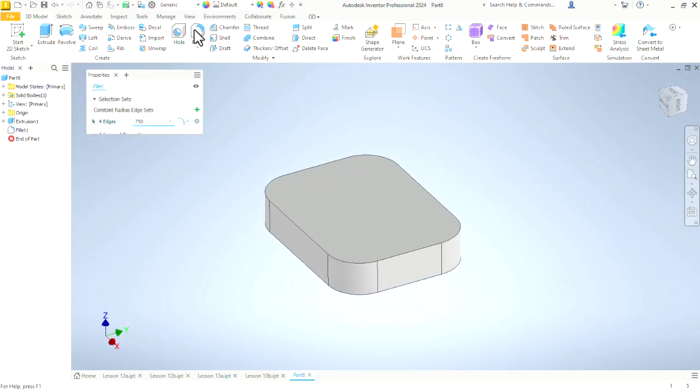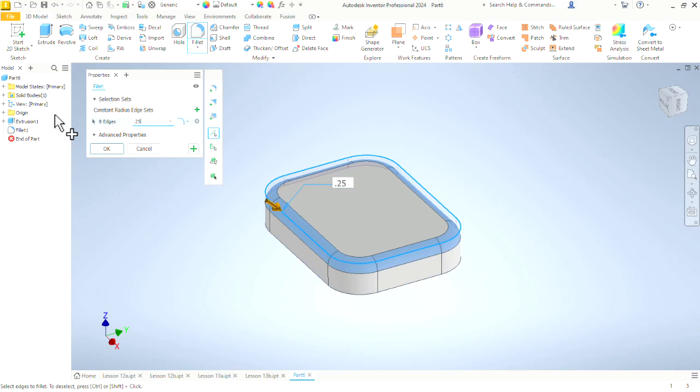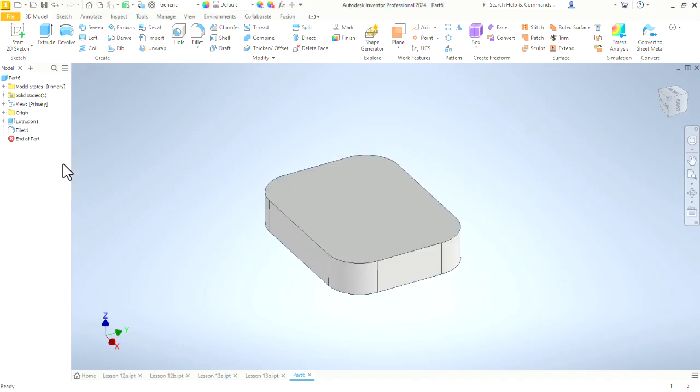If I wanted a simple fillet, a simple rounded edge, then there you go. That's all you have to do. Do a fillet, put in a diameter, or put in a radius, say okay, we've got a fillet. But that is not what we want on this one. We want something a little more complex. And we need to create a sketch of that.